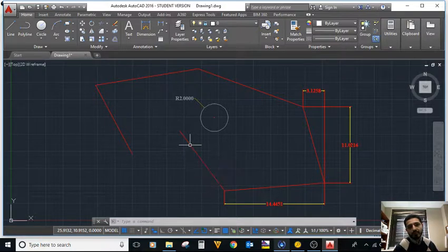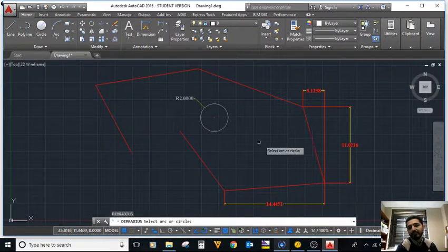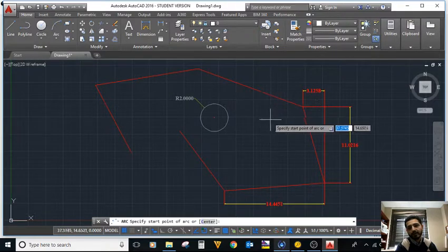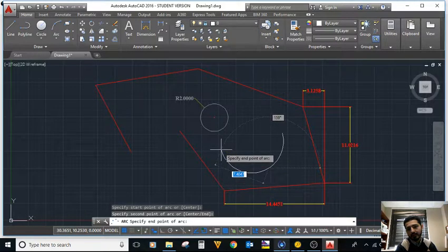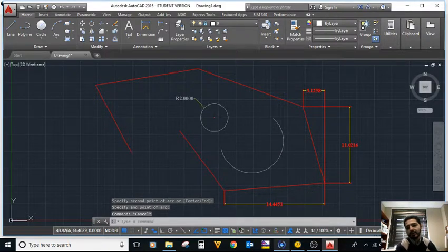So where do we get it again? It's the dimensions, and you put here, as I said, DRA. That's the command for the radius. It can be for an arc, it can be for a circle. For example, if I want to draw an arc real quickly, and this is an arc. Again, an arc is a part or a piece of a circle.